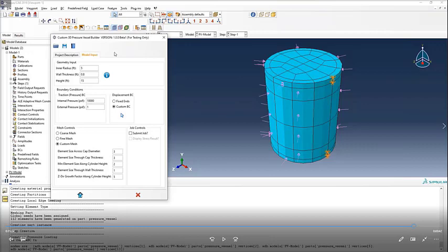Scripts can call other scripts. Obviously, depending on the complexity of your design of experiments, the power of Isight, and being able to combine multiple tools, gives you more flexibility. But if you're just working directly within Python and Abaqus, then I can't see why you wouldn't be able to create the whole workflow with Python.